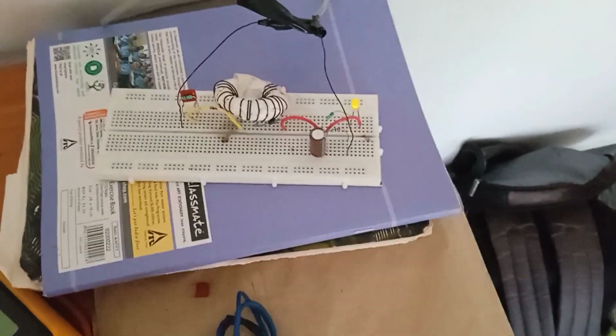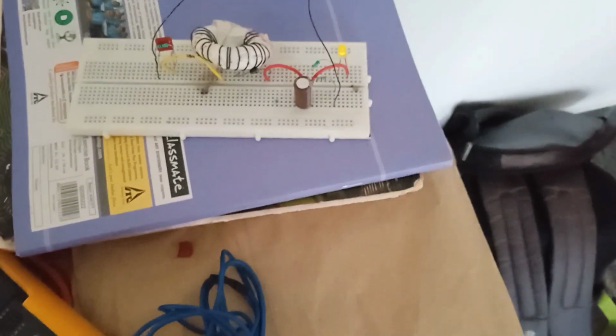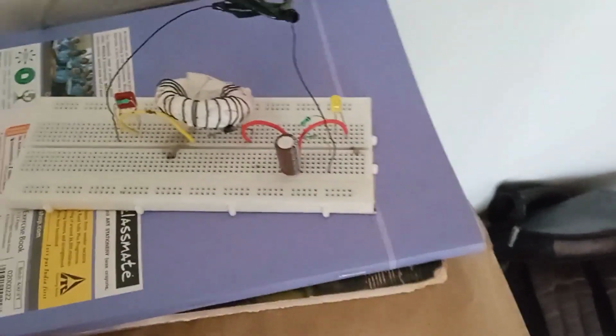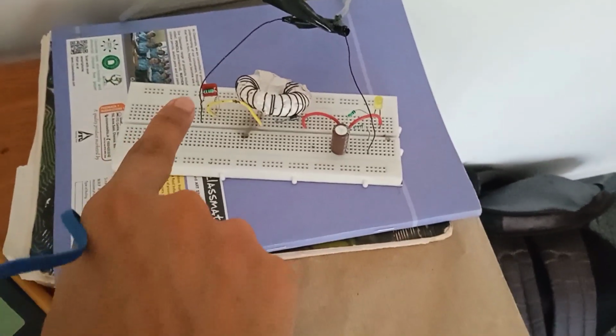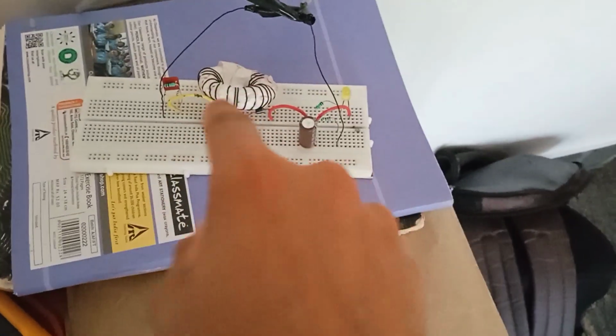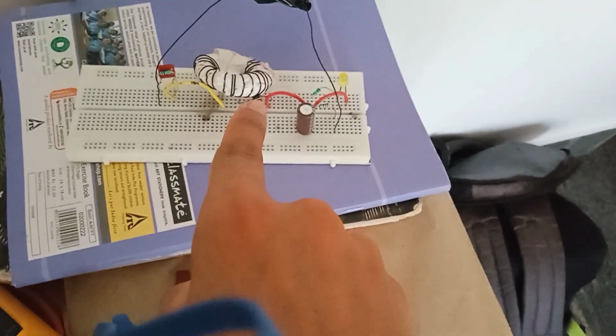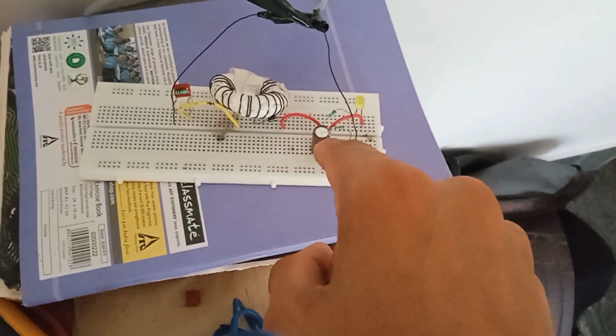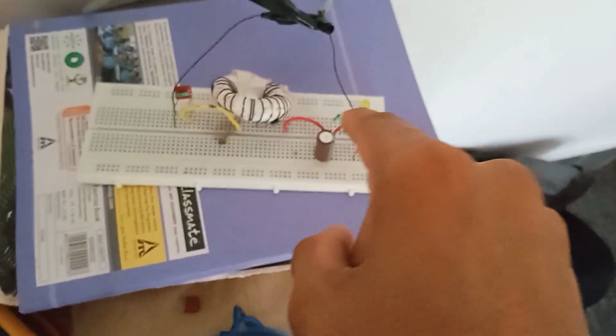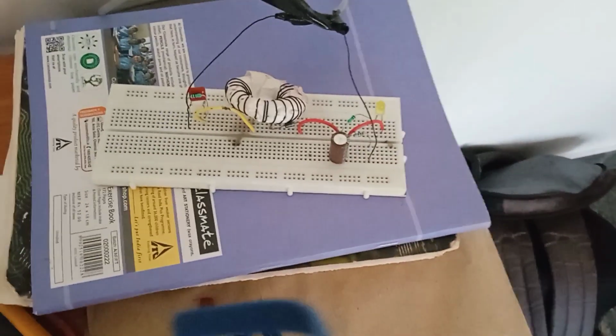Let's do some measurements. The voltage and those things you can measure with my beautiful multimeter. Here is the 240 volt AC. Here the voltage drops, this inductor is doing some power factor things, and this diode is rectifying things. It's around 100 volts here, and this large resistor is to limit the current.